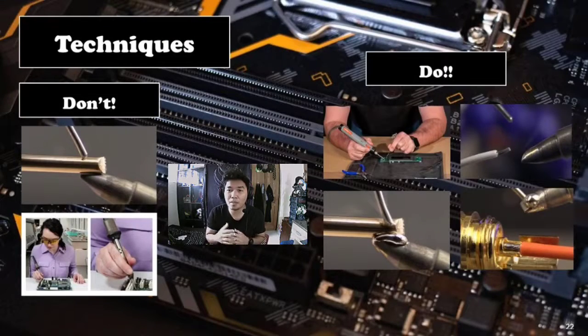Now, here is something that people have been trained for many months, for many years, in order to conduct the soldering process. From here, you must always be reminded that whenever you want a good soldering product, you must always put some tin on top of the soldering iron for the conductivity, as it will act as a thermal conductor. From here also, you must put some solder between two elements, which is also counted as pre-tinning, for the surface of the copper wire and onto the tip of the soldering wire. Hereby, you can make sure that the fluxes of the soldering are spread evenly throughout the soldering material.